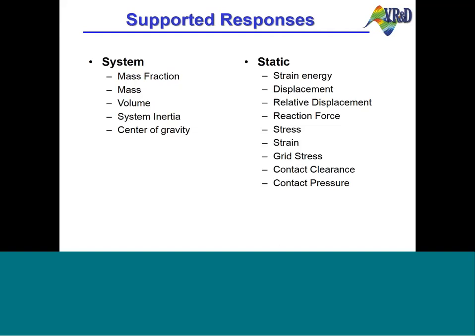Okay. Essentially, when you define a stress constraint or stress as an objective, you are specifying the areas or the elements where you want to use the stresses for. And if you know that there is a stress concentration in a certain area, you just leave it out from the specification of the stress responses. In other words, you leave out the elements where you know that there is stress concentration, and only use the elements that you are interested in.